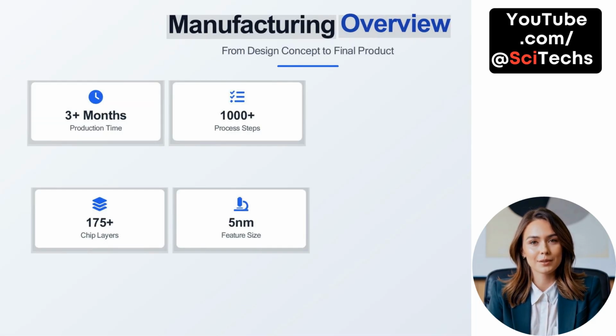Manufacturing overview, from design concept to final product. Semiconductor manufacturing is one of the most complex and precise production processes in the world. From the initial design to the final chip, the journey typically takes over 3 months. During that time, each chip goes through more than 1,000 individual process steps, including deposition, lithography, etching, doping, and inspection. These steps are repeated in intricate sequences to build up the many layers of the chip.